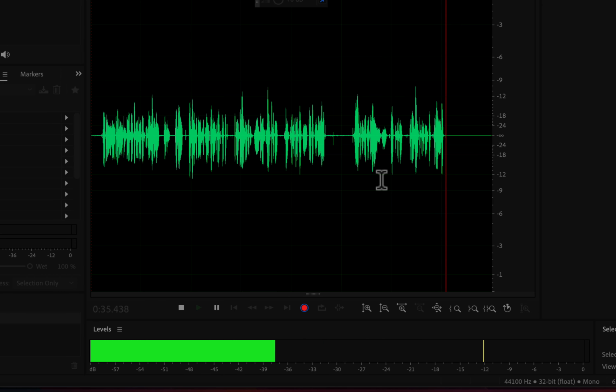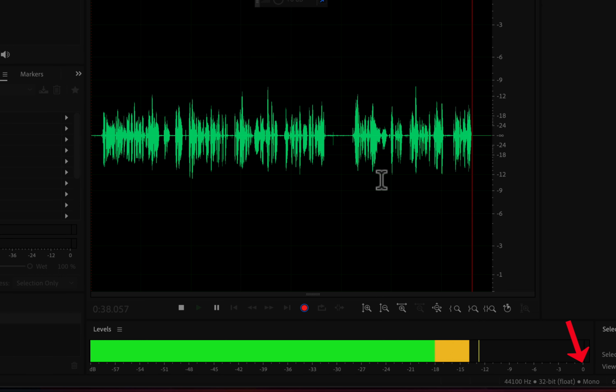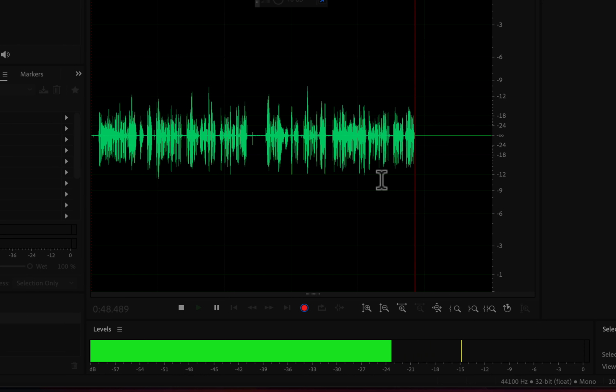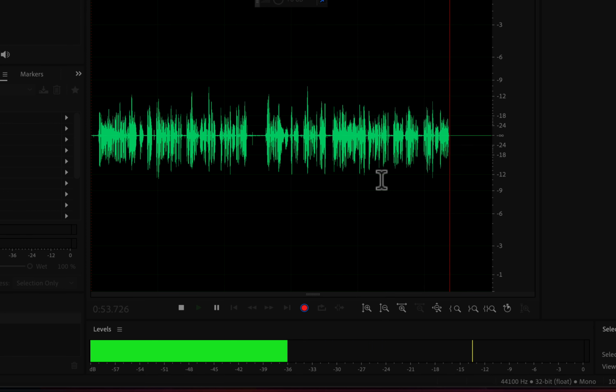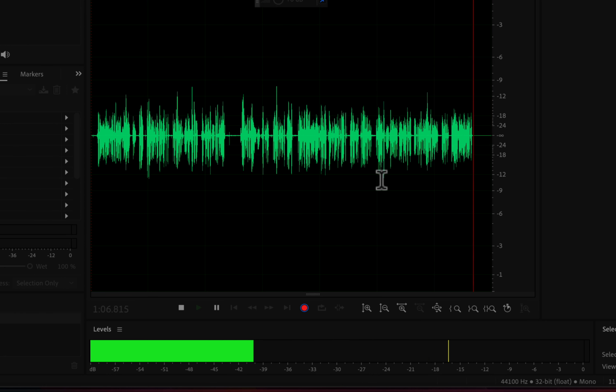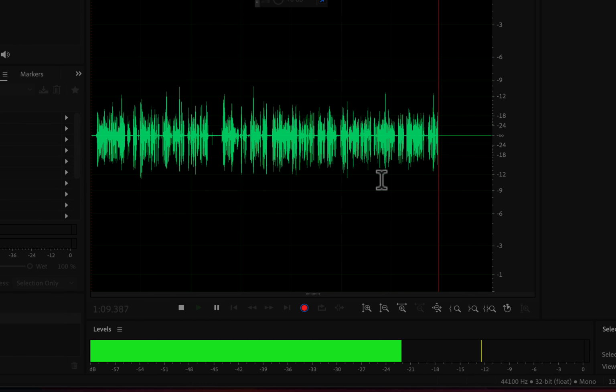So why is that? Actually, you can see that 0 is the maximum value in this meter, and if you go beyond 0, then the sound becomes distorted or clipped, and that does not sound good. So to avoid those kinds of situations, you should record at -12, and that will give you some headroom. Headroom means from -12 to 0, you will have some space. If you increase your loudness in that range, then it will not have any clipping. But if you record at -3, then you will have a headroom of only 3. If you boost your audio by 6, then that will result in clipping.